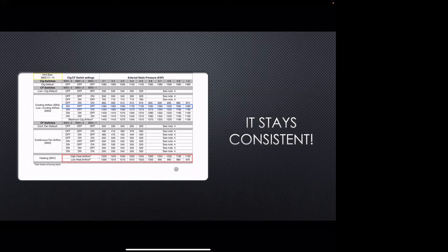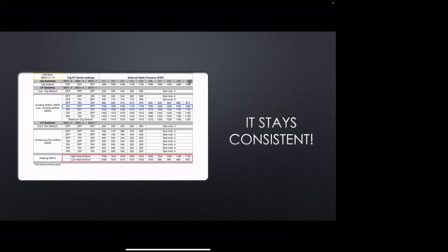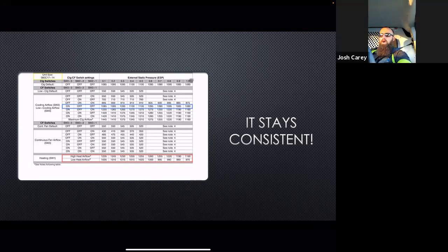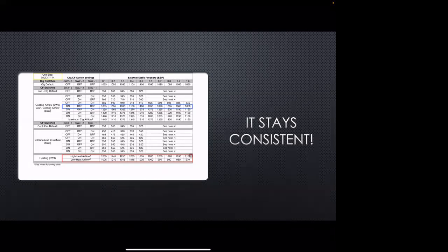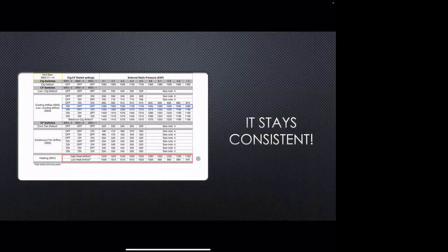Where do you think this pressure is going to be on this unit that we just upgraded, even in low stage airflow? It's all going to be on the motor. But what's that? Low, is it going to be? Low stage probably about 1.1, high stage 1.3. There you go, that's exactly it. So we're off the chart, right? They don't give us this part of the chart, that blower performance fan curve. They don't give that to us for a reason. We don't want to be there.